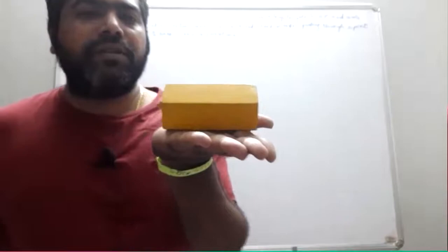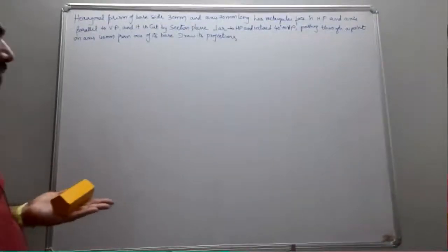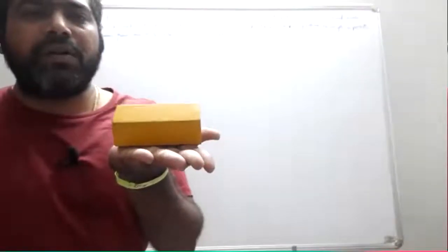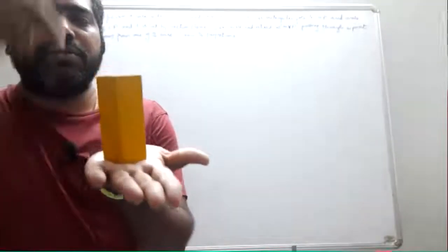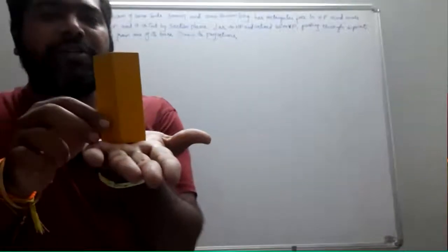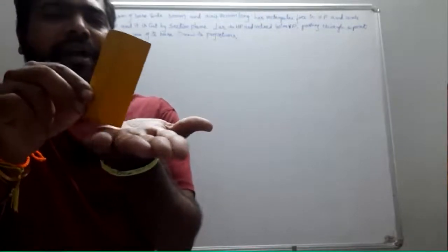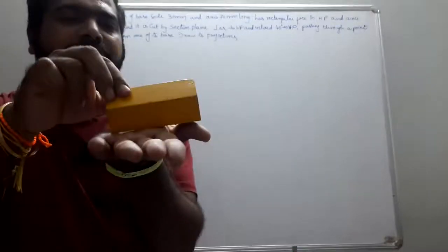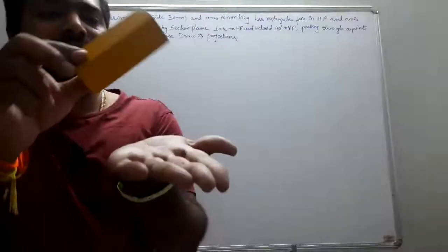So we don't do it like that. How can we do it? Let us assume first that the rectangular face is going to be on the ground. For that, first see that the axis is perpendicular to HP. Once you obtain the axis perpendicular to HP, you tilt it in such a way that the rectangular face is on the horizontal plane.